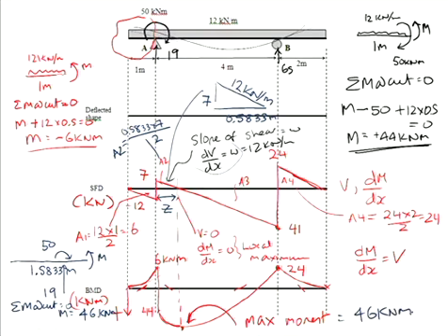If you want, you could calculate that area, take it away from area 1 and take it away from 50, but you're going to come up to me after and say, do I take it away or do I add it? And what I would say is don't use that method if you're confused. I don't use that method when I'm confused. I cut the beam. Equilibrium works every time. Is everyone okay with that part of the question now? Okay. Go away and have a look at it again.